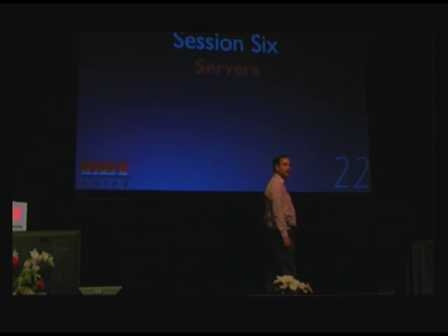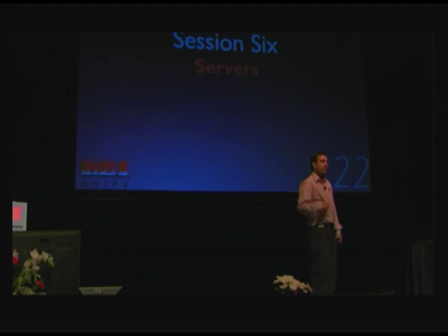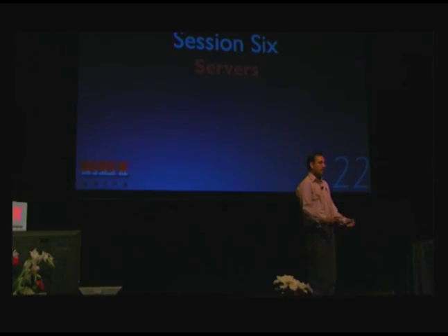C6, we actually flush the mid-level caches in the core. You could have stale state that could cause you to snoop it, but you do flush the caches, and you don't have to wake up the core every time you need to respond. Because the caches are flushed, you can spoof a response. That holds true for the other socket which is trying to snoop out the data from this particular socket in which one of the cores is in C6. So that address has to be blacked out for that particular cache, or how does it work?